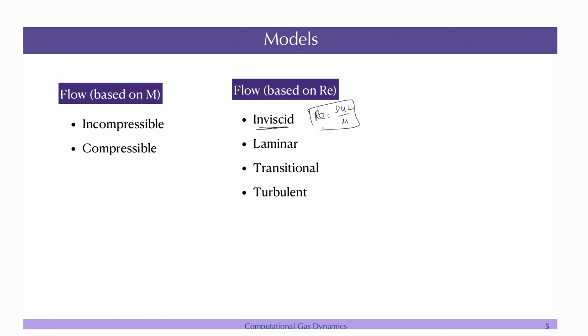Okay. So if you have an inviscid solver, you can just say okay, viscosity 0. That means you are solving an inviscid problem or Euler problem. So the equation will also change accordingly. All the viscous terms that you have, you can explicitly remove. Or if you have a viscous flow solver, you can set the viscosity to be 0, so that their influence is not coming.